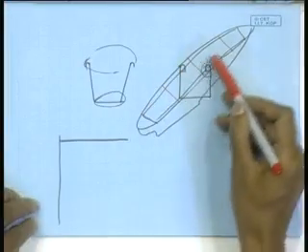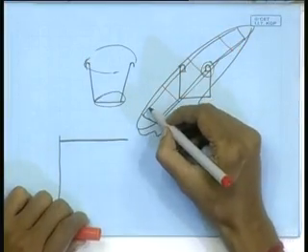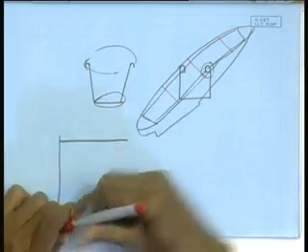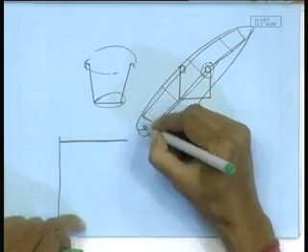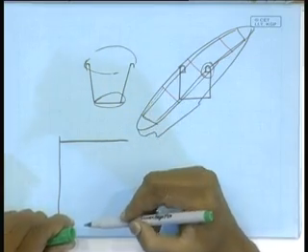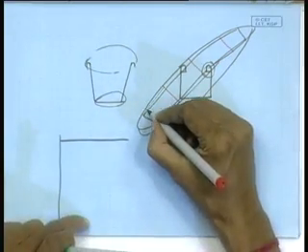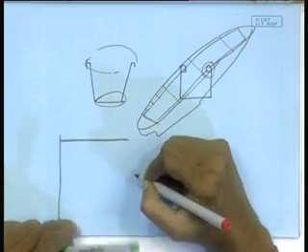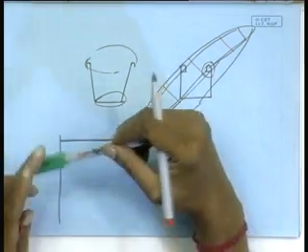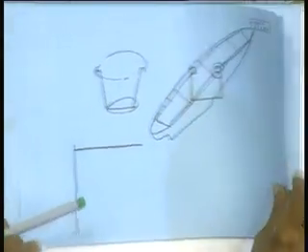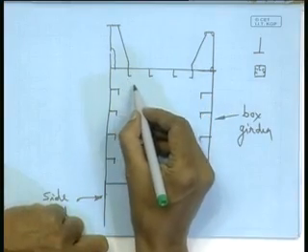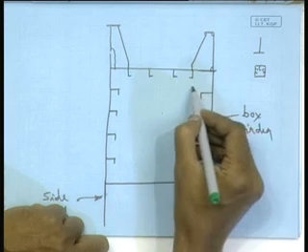So, bulkheads are there. So, in the process what happens, if the bulkheads are there, like here I have drawn in red, these longitudinals in the box girder will be running from one bulkhead to another bulkhead. So, this again becomes quite a huge span, isn't it? So, again from the same logic we will have transverses in between, like we had the deck transverses in the general cargo carrier or bulk carrier, right. So, same logic is there. So, here the transverse means what? Means essentially a plate here, a plate there.